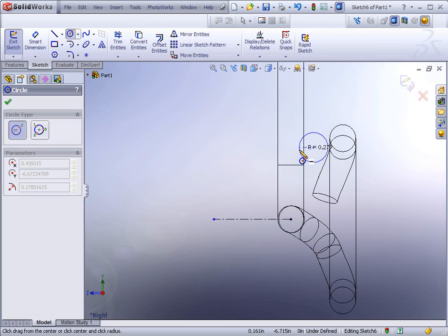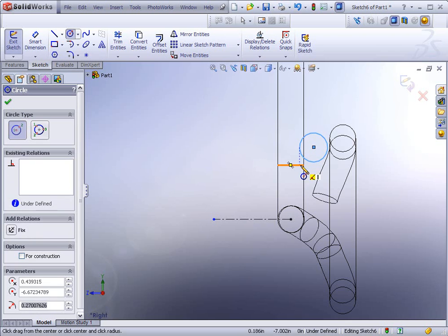Now I'm drawing out a radius of like 0.25 is what we want to get to, because it's a 1/2 inch diameter circle. I'm drawing it just a little bit bigger, and what I want to do is just intersect this model. As you can see here, I'm not drawing it tangent to the edge. If you do that, be prepared that when you revolve it, they're going to be separate bodies. You want to intersect it just a little bit like I have here.